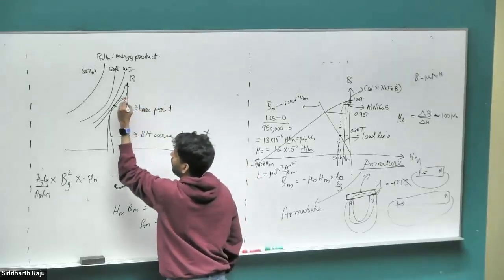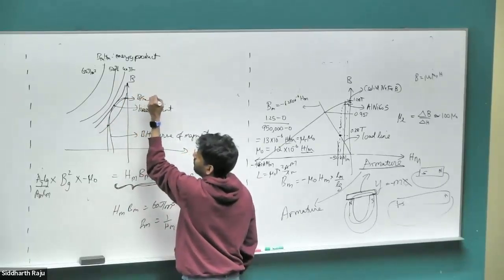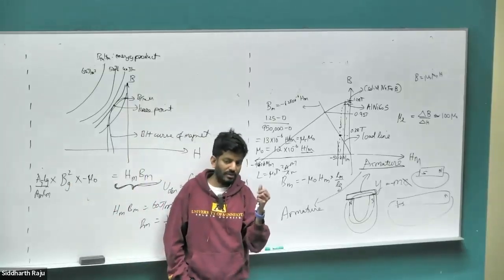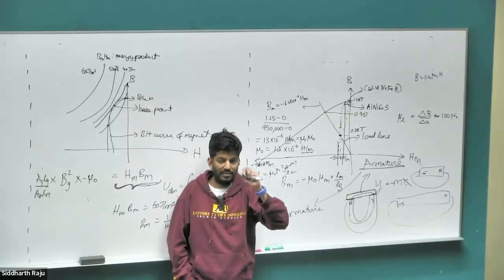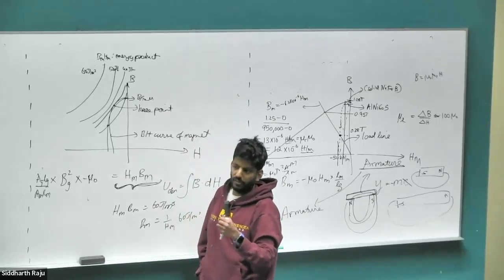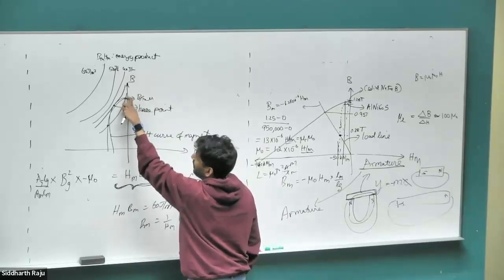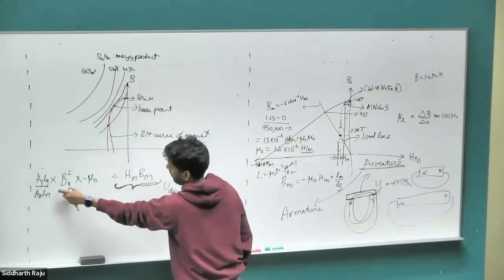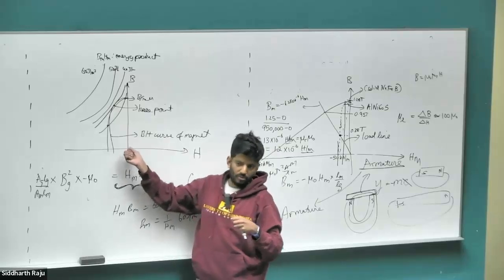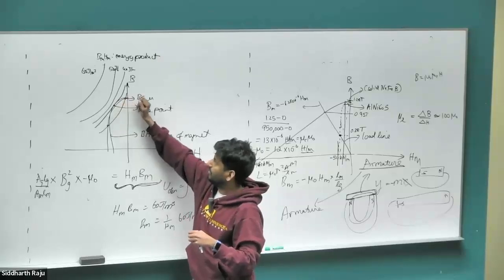If you go any other further lower, you will get multiple operating points, right? You can get higher B field, but that does not mean you can transfer maximum energy to the air gap. So ideally you would think, okay, if I keep on reducing the magnet air gap all the way very close to zero, you might end up with better performance. That is not the case, right? Because if you end up going to a lower air gap, that means the BG ends up becoming higher. That doesn't mean it is the place at which you get the maximum energy travel through the air gap. Because when the BG increased, the amount of HM you can push also reduced at that point. All right, so it's a fine balance between choosing what kind of value you run your BG at.